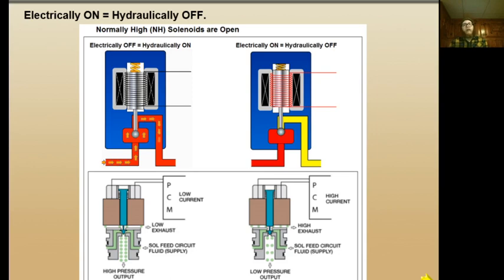The third thing that it needs to do is allow the vehicle to drive at least some kind of speed. If we're stuck in 1st gear, customers are probably going to blow their engine up, because they're going to have the engine just screaming at thousands of RPM, trying to get off the highway or get out of that dark, scary road that they're on, or whatever. So those are the 3 major things, and the 4th element is just what's most convenient, what happens to just work out that way when they're designing the transmission.